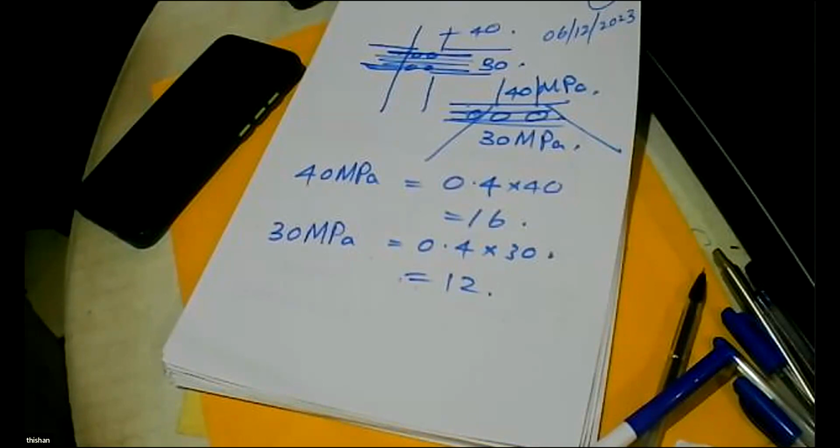These days we are doing a project where, what is the general capacity of a 1,200 pile? 6,000 kilonewtons. What is the general capacity of a 1,500 pile? 10,500 kilonewtons. But in this project, our 1,200 piles of 40 megapascal will carry 11,000 kilonewtons, nearly twice, and our 1,500 millimeter piles will carry 17,000 kilonewtons, all with 40 megapascal concrete and 0.7% maximum reinforcement.